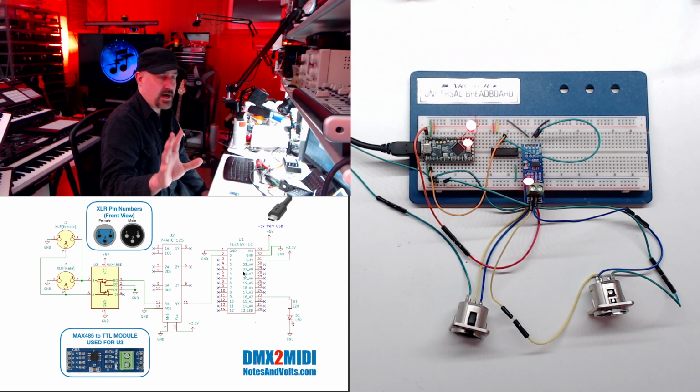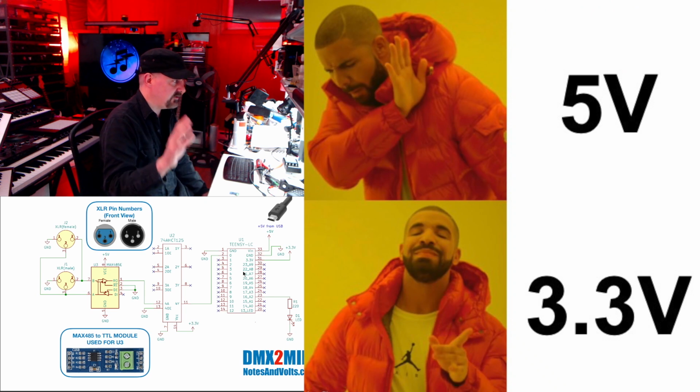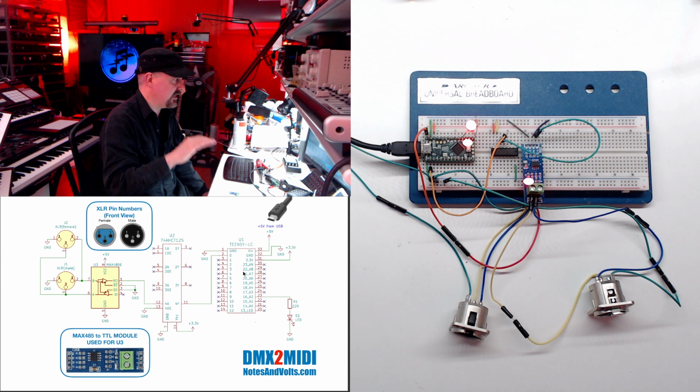Now, one thing to keep in mind, the Teensy LC is a 3.3 volt device. It will not tolerate 5 volts. You cannot put 5 volt signals into it. So keep that in mind for the rest of this explanation.